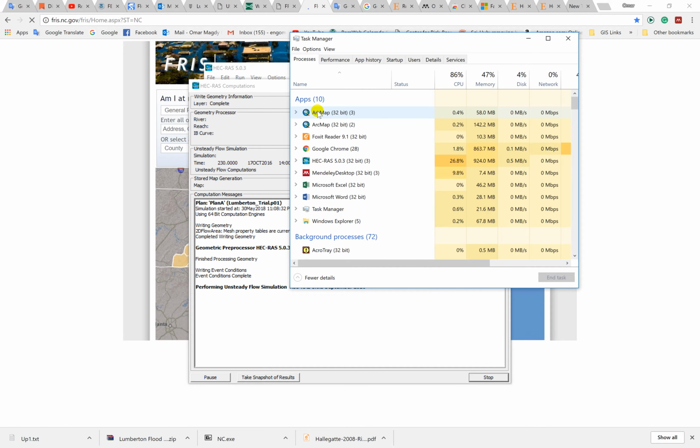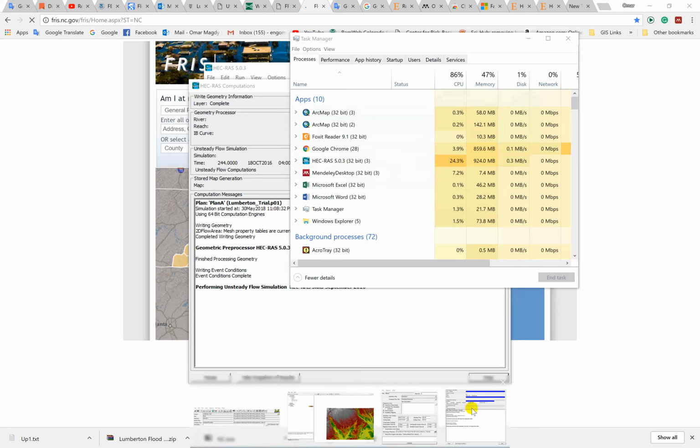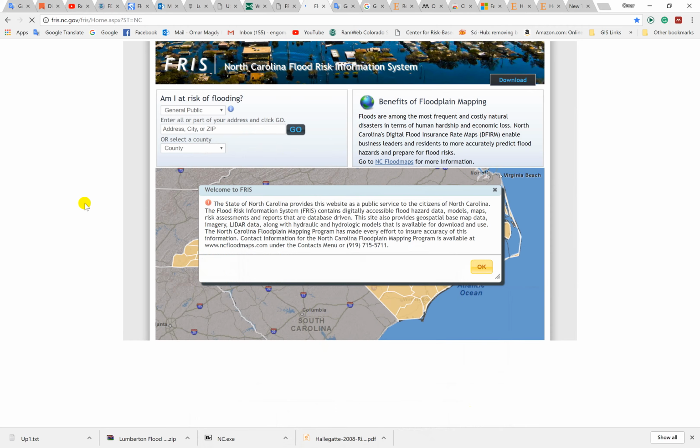Yes, exactly. So let's say that you have a depth on a specific building. You have a depth of flooding, and then based on this depth of flooding, you go to the depth damage function. You will get the percentage of damage. Actually, it's easy. Yes, it's really easy. If we have the flood and we have the building levels, we put them together, we get the flood height, using the damage function we get the percentage damage, multiplied by the replacement value, we get the damage cost. Yes, exactly. If you want to use it, I think it will be helpful.